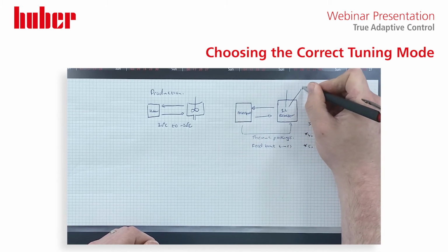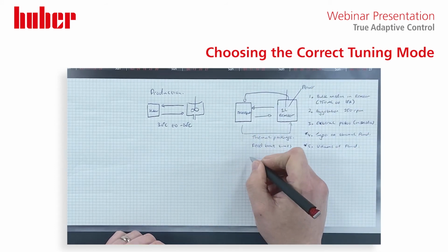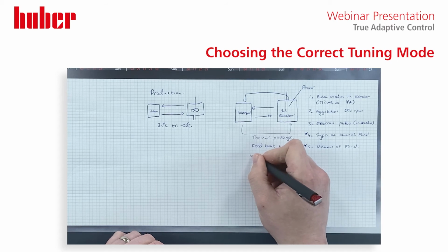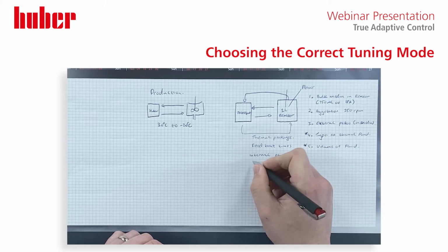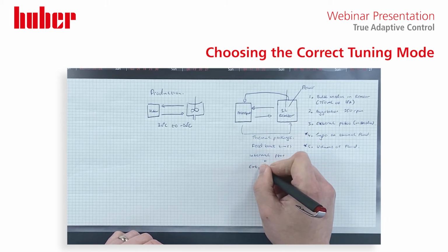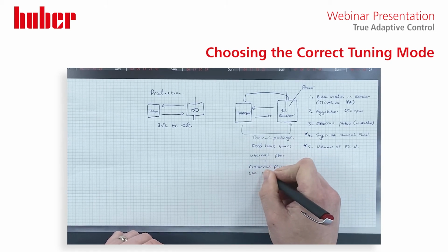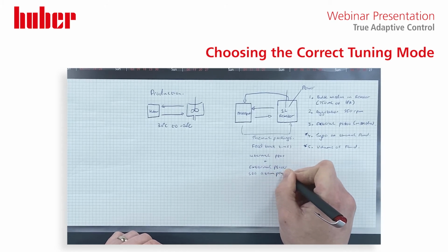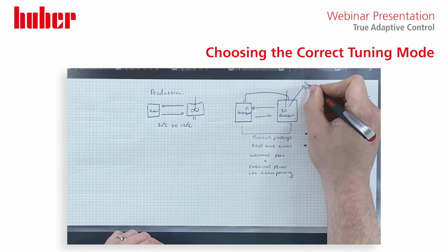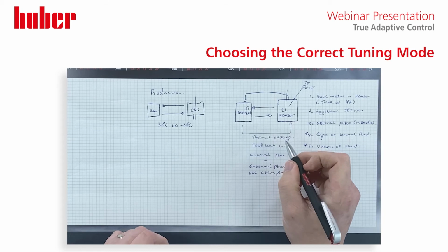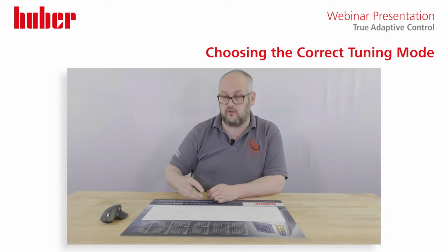In this case here, we've got a feedback loop. It's looking at how quickly the internal PT100 and the external PT100 see a temperature change. So we have TI in here, we've got TE here. Sometimes on the Unistat Ranger family we also have a TR, so you can look at your return temperature.